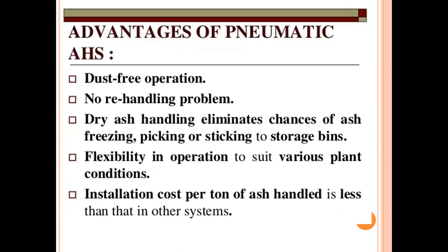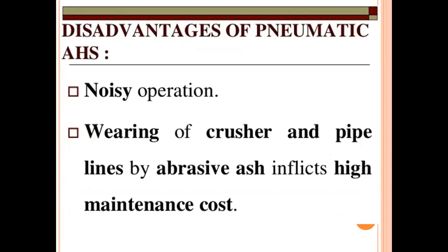Advantages of pneumatic ash handling system: dust-free operation, no re-handling problem, dry ash handling limits chances of ash freezing, sticking in storage bins, flexibility in operation to suit various plant conditions. Installation cost per ton of ash handled is less than that in other systems. Disadvantages: noisy operation, wearing of crusher and pipeline by abrasive ash, which inflicts high maintenance cost.